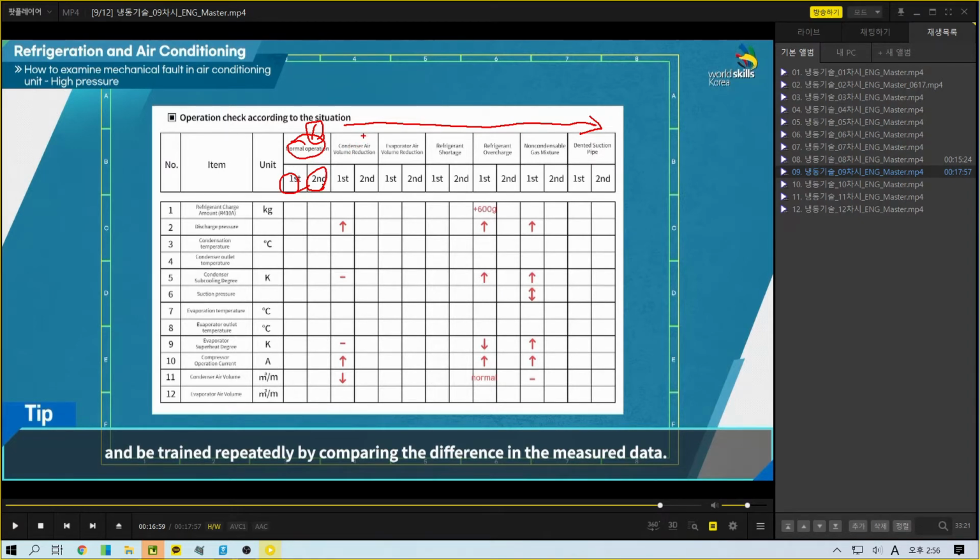The first 2 sections are about the evaporator and the condenser part, the air volume shortage. So it is quite easy to cause the fault by just adding some paper, and removing it.